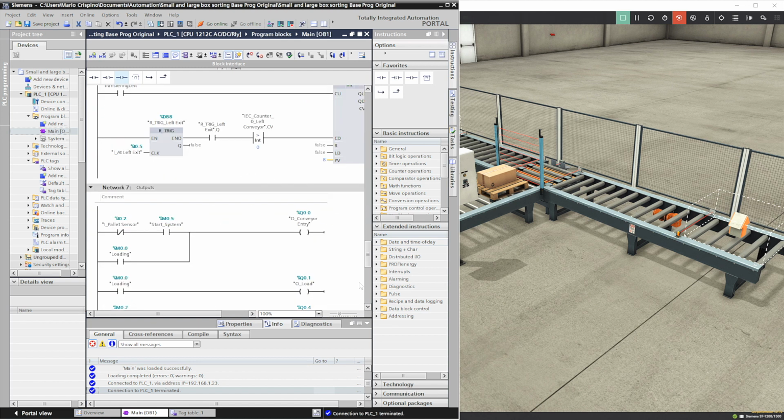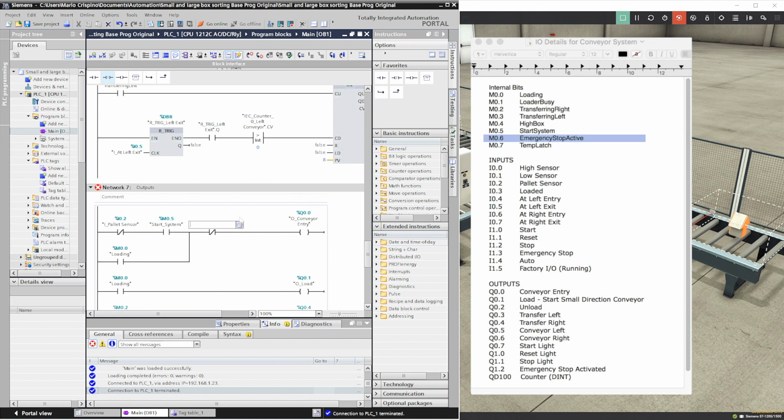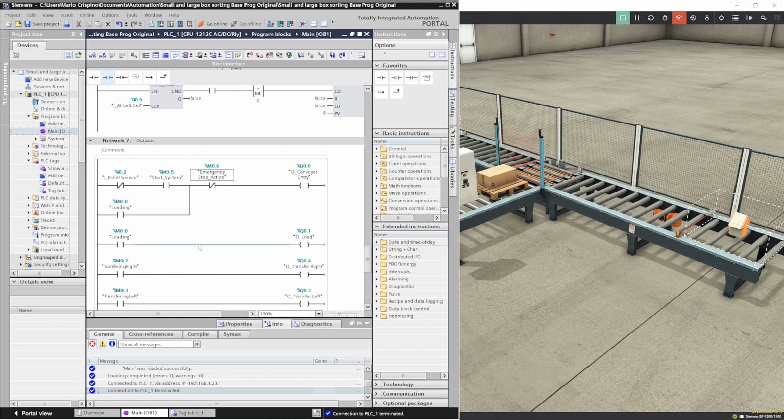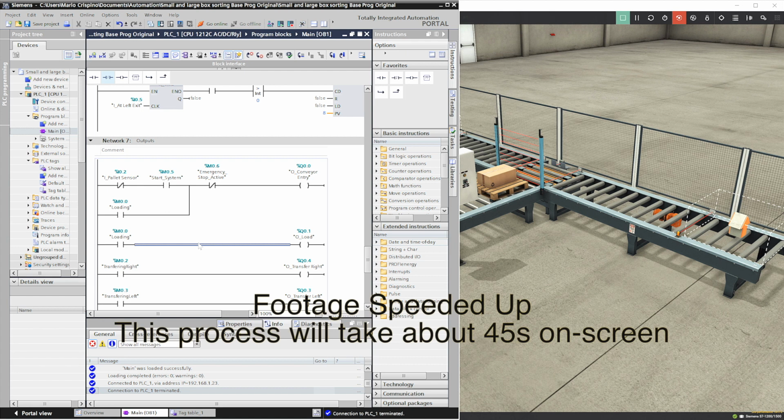So we'll do this branch by branch. Okay, I should be able to do this without thinking too much. So we just have to enter the normally closed contact, address it, and then enter. As simple as that, really. So I'm just going to continue putting them all in now, so I might go silent for a while.